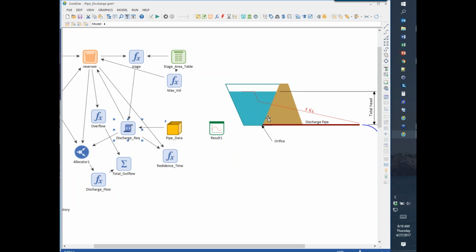The point is that when the water level gets too low, down to the zone of the pipe, then the flows that it calculates are actually higher than what is real for this particular equation that I have, which is for assuming a full pipe discharge here. So obviously it gets more complicated when you get to a non-full pipe down here at the bottom.